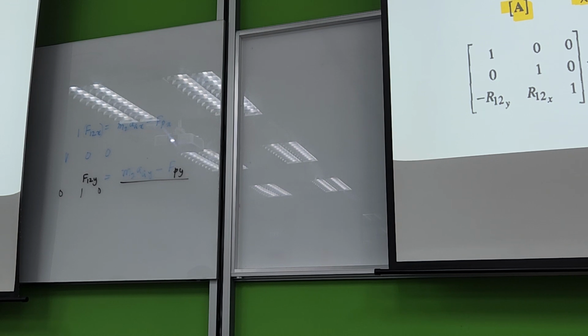I guess we can calculate based on mass, if you know the mass and the length of the link. The alpha value will be given to us. Similarly, the x component of the position vector rp, then the force vector, the x-y force vector at point P, we are able to calculate. So we know this matrix C, we know matrix A, then we need to calculate matrix B. That means we need to know the F12, the force acting on 12, and the torque acting on 12.